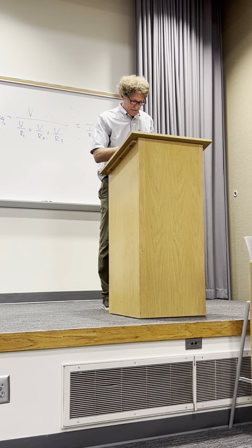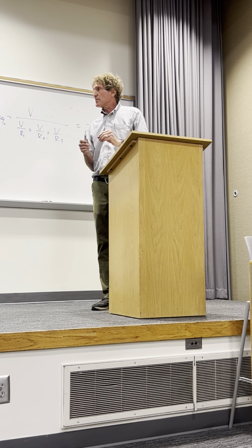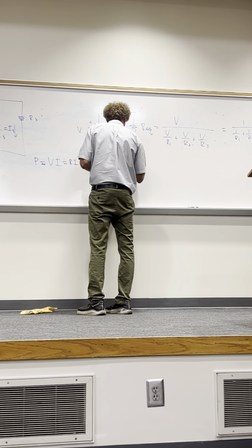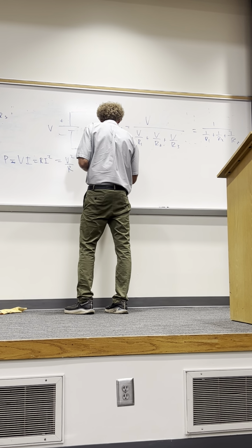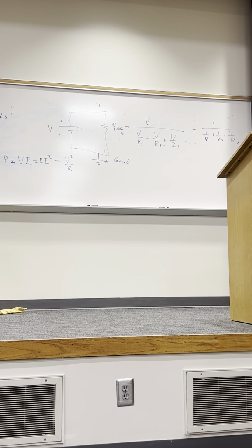All right, now, the next thing, a very simple thing, is what I showed you a second ago, and that was a symbol that I didn't address. This is called the ground. How many are familiar with the term electrical ground in any application at all? I don't care if it's just you're in high school and you have to connect batteries. What I told you about earlier, the ground is the point that's considered zero potential, that everything is measured with respect to. But I do need to be clear about this, especially for mechanical and civil engineers.